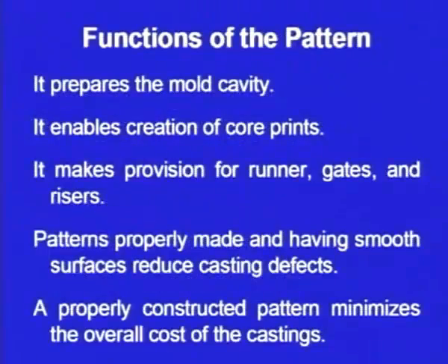And what are the functions of the pattern? First function is it prepares the mold cavity. Whatever component or whatever shape we are going to make, we use a pattern of a similar shape, and when we keep the pattern inside the molding boxes, we ram the molding sand, we compact the molding sand. After compaction is over, we remove the pattern and there will be a cavity whose shape is similar to that of the casting that we are going to make. So it prepares the mold cavity.